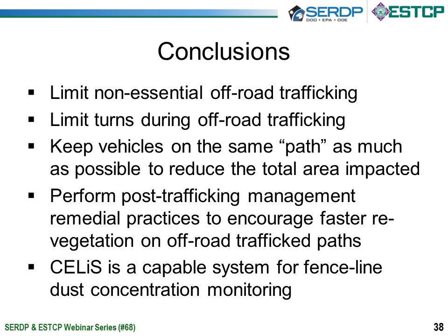The heavier the vehicle, the greater the shear forces impacting the surface when turning. The same applies to tracked vehicles because the tracks tend to shear the surface rather than attempting to slide over the surface when turning. Since the damage is cumulative, but greatest for the initial pass, it is usually desirable for heavy and/or tracked vehicles to follow the same path as much as possible to reduce the total surface area being impacted, even if the cumulative effect of multiple passes increases the susceptibility to total vehicle dust emissions at the time.